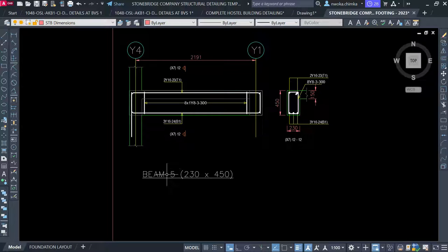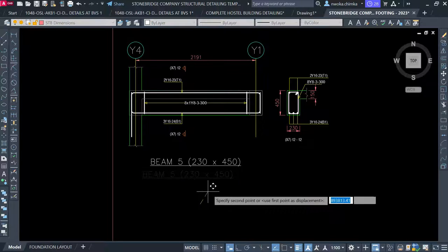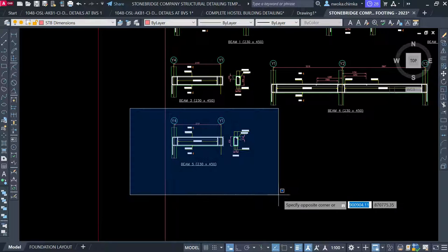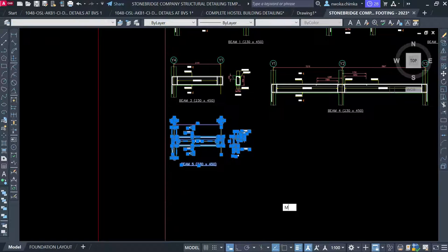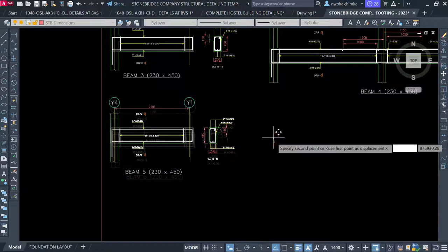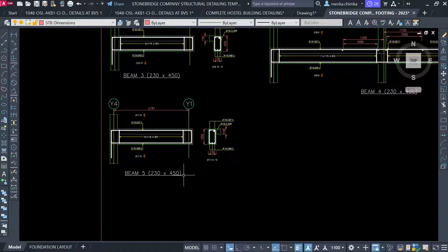Okay, so I'll just go again and do this. But you have already seen how all our beams are being optimized, as you can see there, and how all our joint details are coming out perfectly, which is not how it was after your design in Prokon Structure. Okay, so right now we will go and group for beam 6 because this is beam 5.